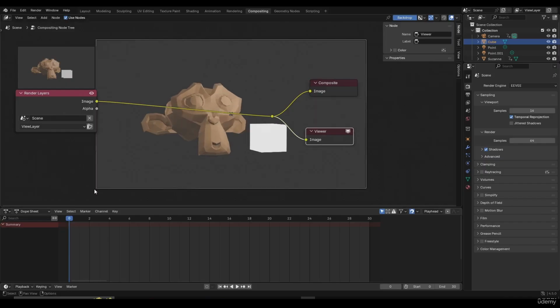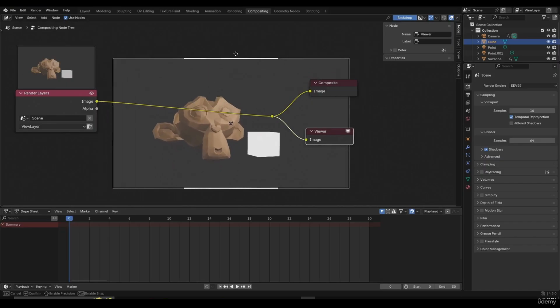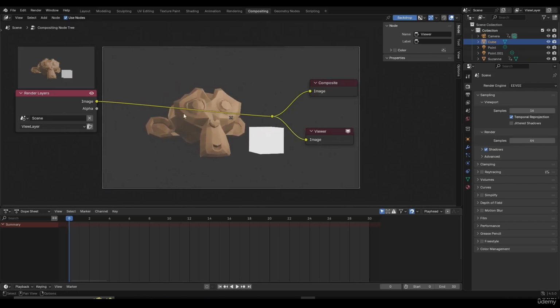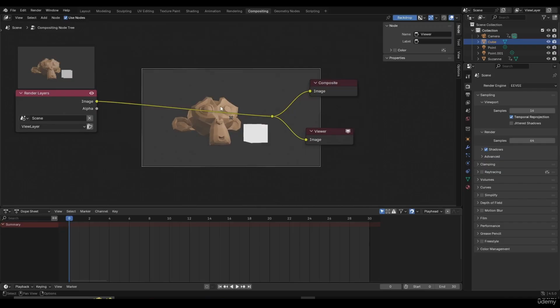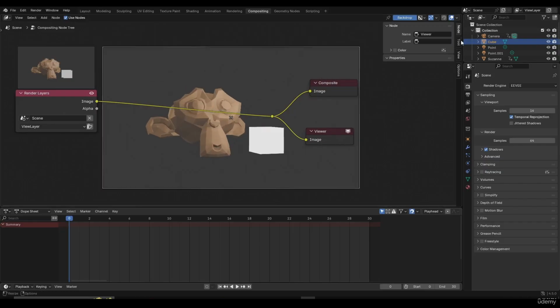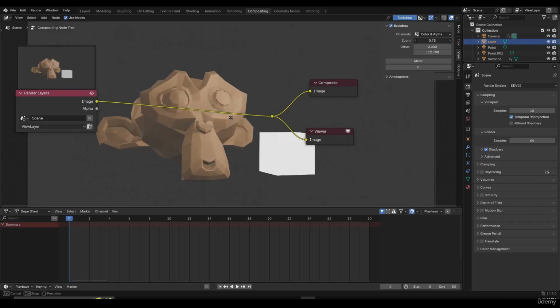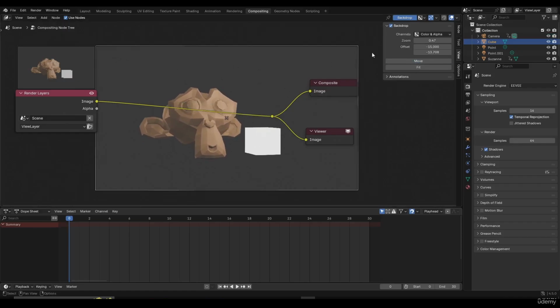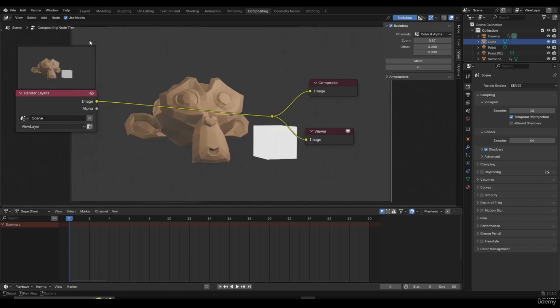Now, I think in Blender 4.5, you can actually go to the borders and then shrink it down or up manually. But if you're using older Blender versions, you can't really do that. You only have to use the shortcuts either V, Alt V, or you can also go to View, for example, and then change the zoom from here, change the move here. And if you want to fit the image on the entire window, I can press Fit, and it's going to fit it like this.